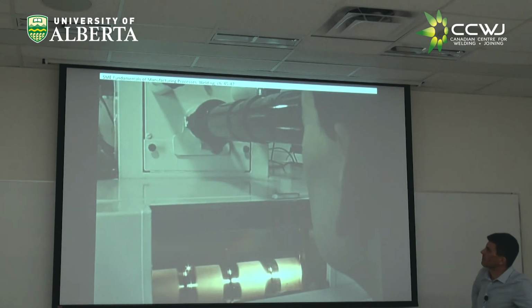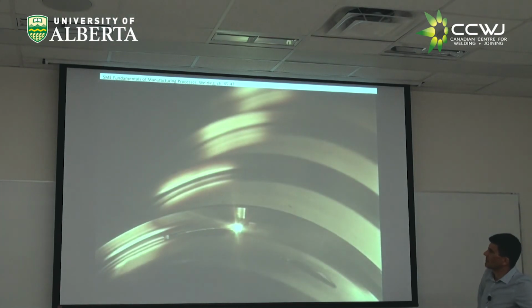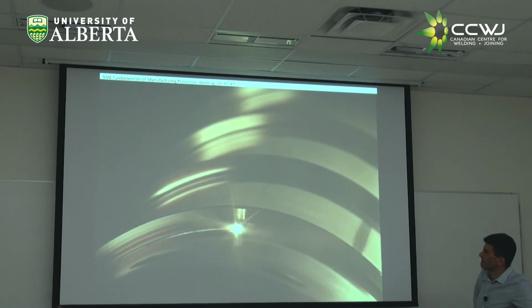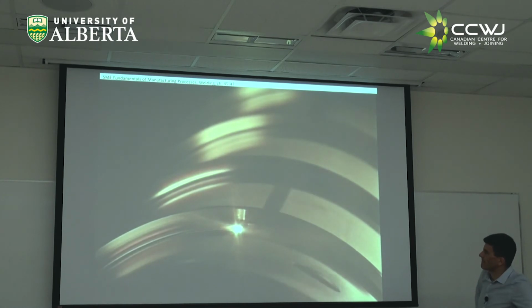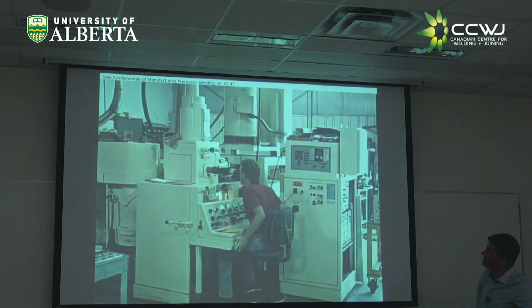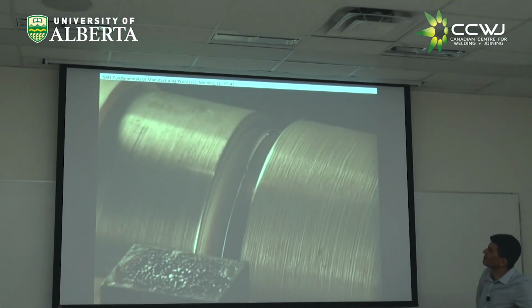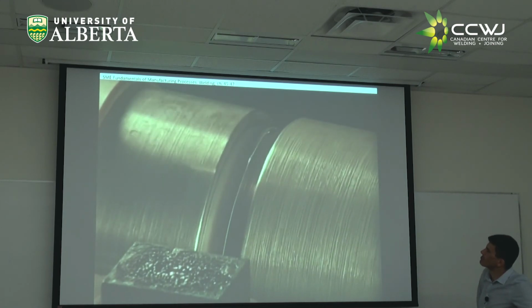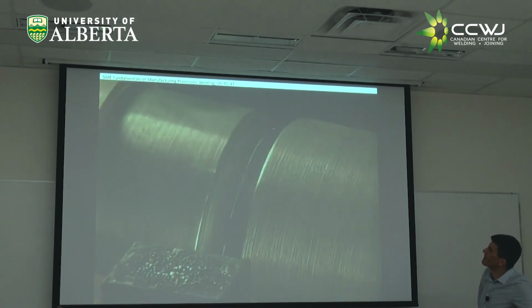Additionally, joints inaccessible by other welding processes can be welded. Virtually all ferrous and non-ferrous metals, thin or thick, can be joined. Welding speeds are fast, and filler metal is not generally required. Equipment cost for electron beam welding is typically high, and welding is generally limited to machine parts assembled in primarily butt, corner, and lap joints.